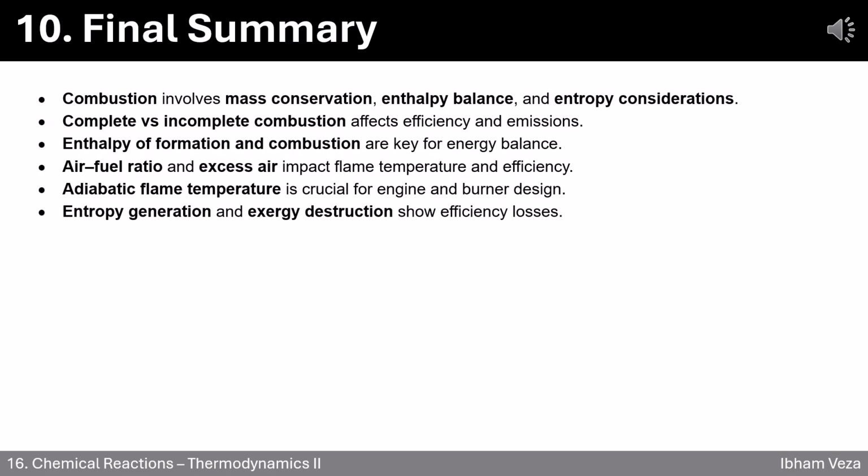We also saw that adiabatic flame temperature is a crucial parameter when designing engines or burners. Finally, by examining entropy generation and exergy destruction, we can clearly see where energy is wasted and how efficiency drops. Mastering these concepts helps you analyze and optimize any combustion system you encounter.